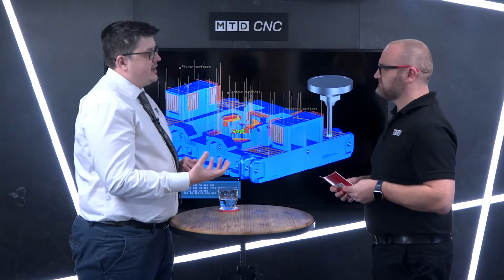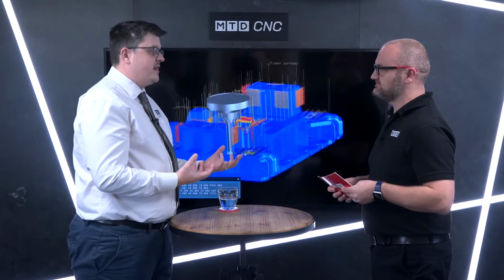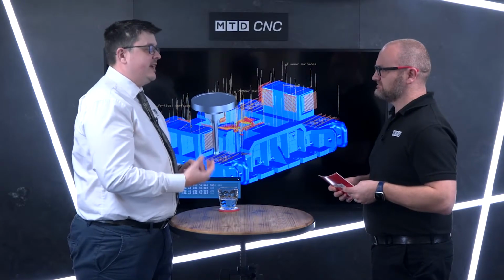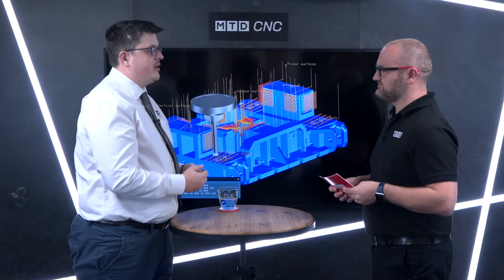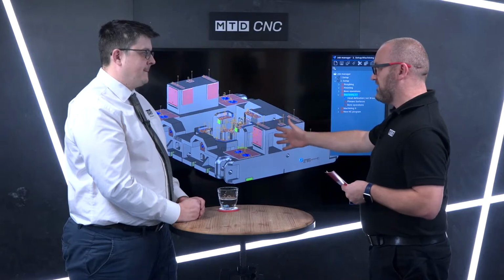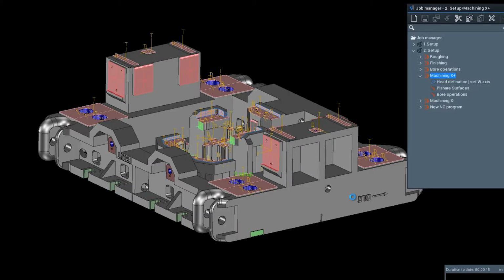The next step with that then is if you use the same NC set to produce an M10 hole, but you've got an 8.5 drill, it knows that it doesn't need to do the milling, so it leaves that operation out. So if we take a look here, it's a milling example of straightforward features. How about more complex features or even turning?